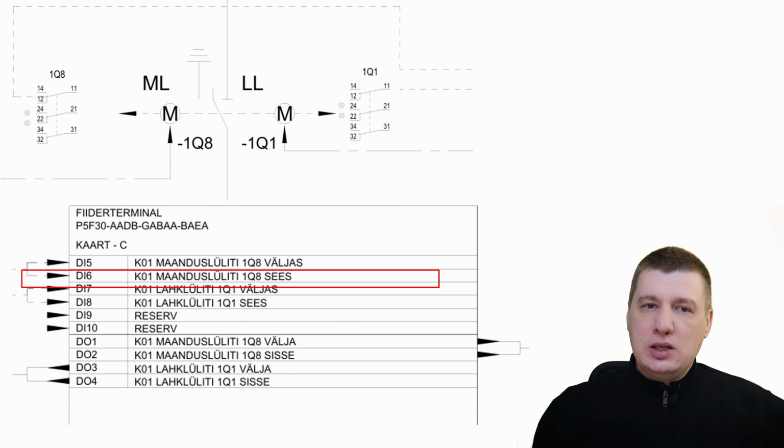How do we verify this status? Firstly, look at the physical panel. Indicator H1Q8 will turn red, which indicates that the closed position is on. At the same time, on the P5 mimic display, the single line display will update. The symbol for the earth switch will change from the open gap to a solid line connected to the ground symbol, providing immediate visual confirmation that the bay is earthed.